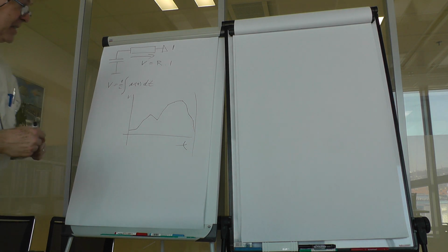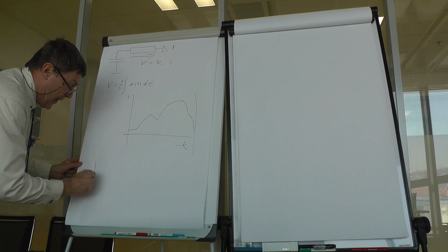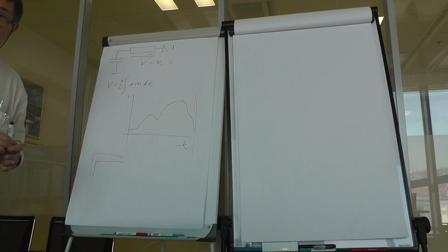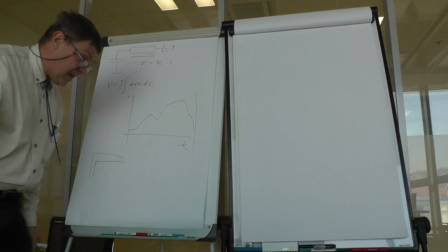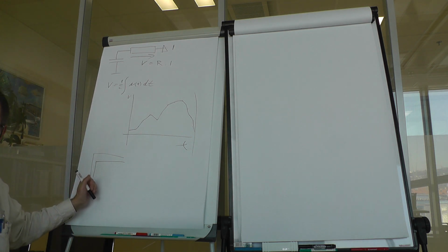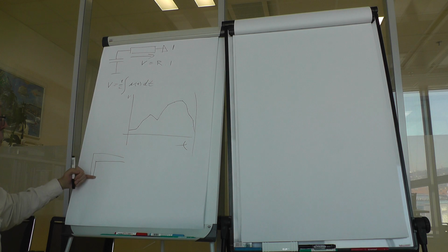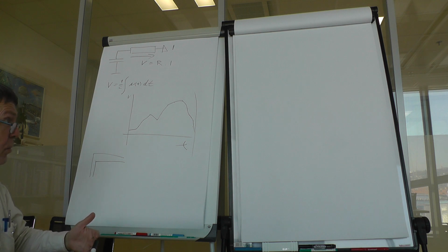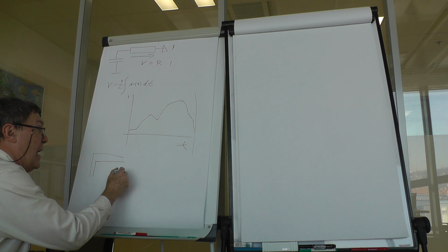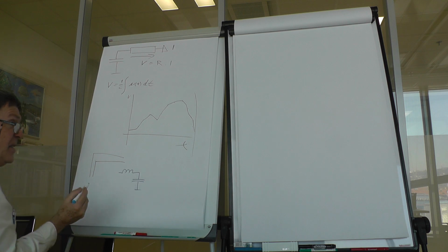What are distributed parameters? Well, for example, we have a transmission line, a piece of connection on the substrate, on the printed board circuit, and this piece is unfortunately in some cases comparable to the wavelength. At this moment we can substitute this by a model which, mostly for a transmission line, looks like a set of sections that are inductors and capacitors.